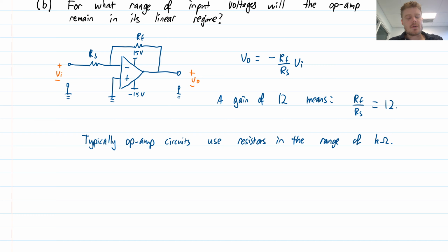So typically from, say, 1 kilo ohm to 10 to maybe 50 kilo ohms, that's kind of the rough ballpark that we expect. If you try to use resistors that are too small, then you place too much demand on the op-amp to produce too large a current. And so your circuit's actually not going to work very reliably. So as a design principle, a few kilo ohms is kind of the bottom end that we would like.